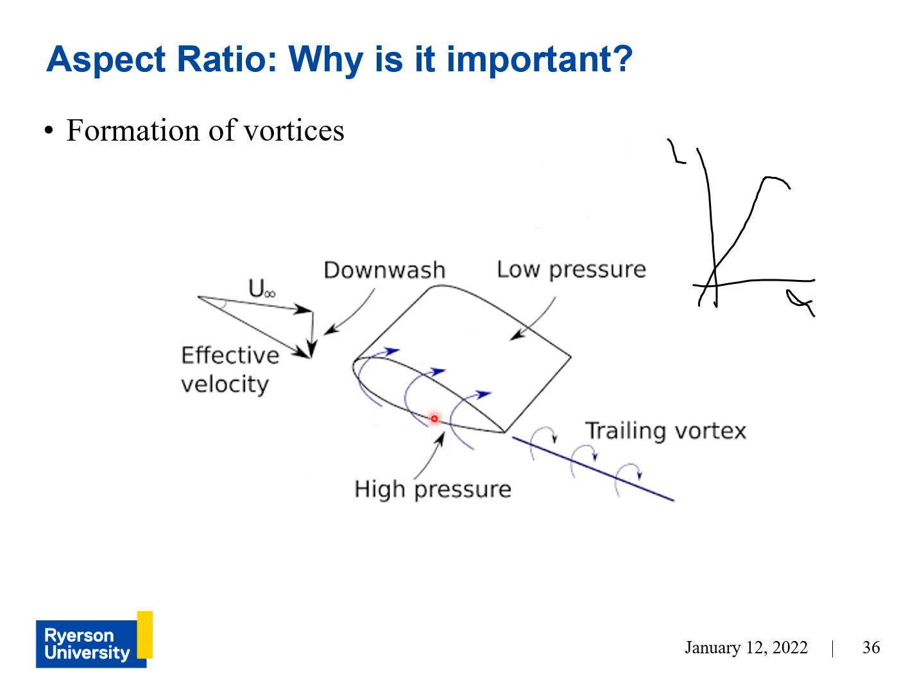And that means that the effects of these vortices forming at the tip of the wing will be less than, let's say, a lower aspect ratio wing where the tips are closer to the rest of the area of the wing. So that's why it's important to understand the advantages of having a higher aspect ratio. It's because it's sort of separating further the effects of this formation of vortices away from the rest of the wing.